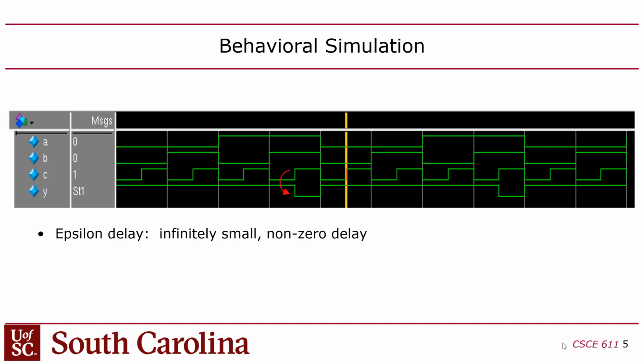But when that happens, it happens seemingly at the same time. And in fact, when you look at that, you're almost like, wait a minute, how do we even know from this timing diagram that Y dropped as a result of C rising from 0 to 1? I mean, they're happening at the same time. It's almost impossible to tell that there's a causal relationship there, right? Because in Model Sim, it's like instantaneous, right?